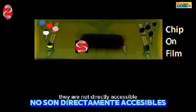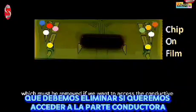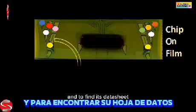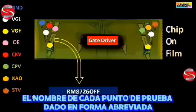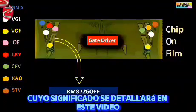They are not directly accessible because they are covered with an insulating material which must be removed if we want to access the conductive part. To know the name and the function of each test point, it is necessary to note the name of the chip registered on the COF and to find its datasheet. Here, we are interested in the chip that drives the rows, called gate driver. The name of each test point is given in abbreviated form, whose meaning will be detailed in this video.